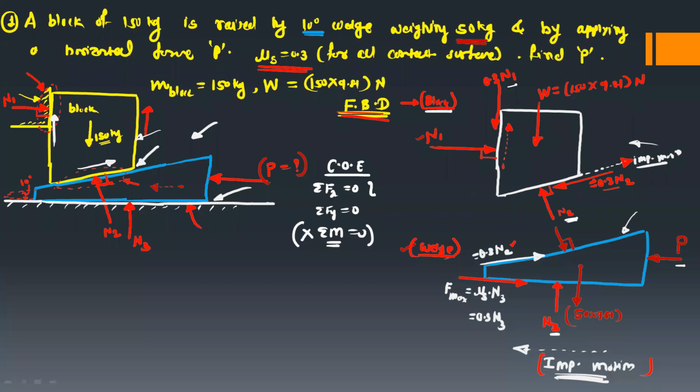So the available conditions for equilibrium are summation Fx = 0 and summation Fy = 0. So select the free body diagram having only two unknowns. We have to select the block first. So consider the block free body diagram and then use the conditions of equilibrium. First I will use summation Fx = 0. Now write the summation Fx.